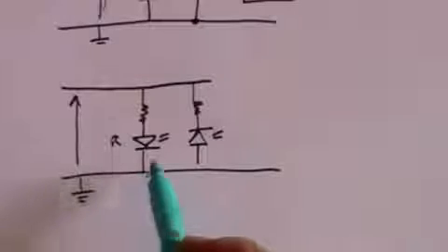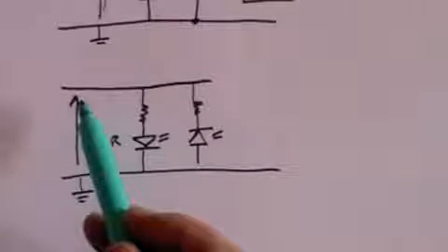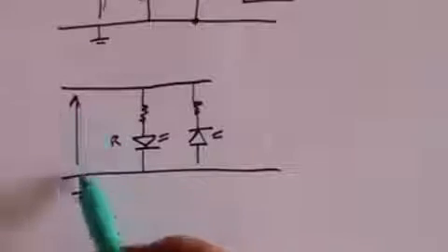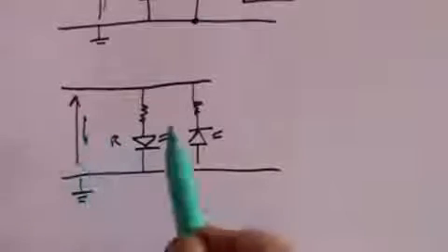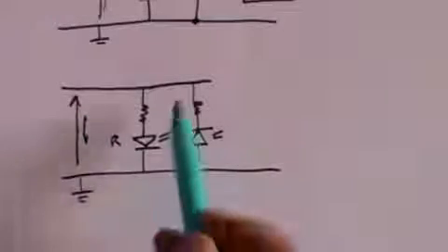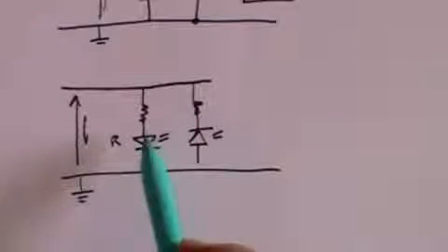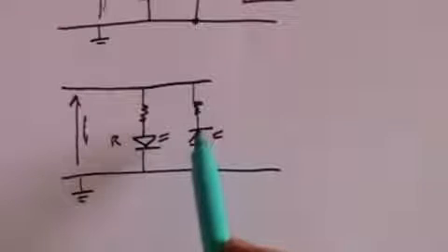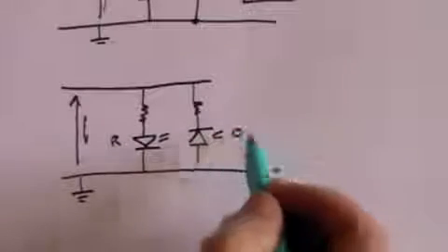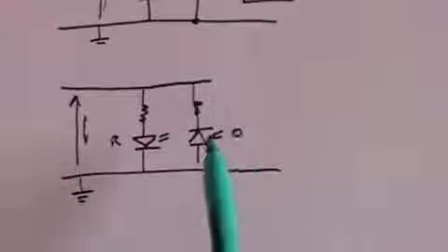and that red diode will then glow. If at any stage the voltage flips, so the voltage is now negative, pointing in this direction, that means currents will flow upwards. Well, they can't flow upwards here because that's the wrong direction for the diode, so they flow upwards through this diode, which is, say, the orange. So what you've got now is if the red light is on, that means you've got a positive voltage and the current is flowing that way. If the orange light is on, that means you've got a negative voltage and the current is flowing that way.